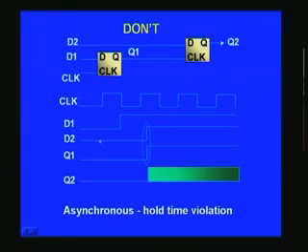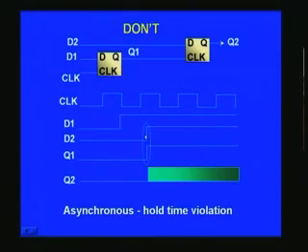So actually these are all the steady state of the previous clock, so normally this will not pose any problem. And only here, that means it already satisfies the setup time. And what is going to be violated is the actual hold time. When the clock rises, the data is not stable. As per the hold time, this data will have to be stable for at least a TH time. Beyond that, naturally this is violated, and you have no control over that.